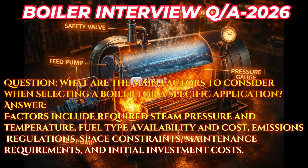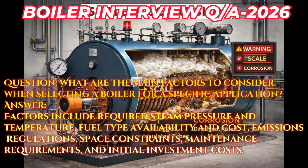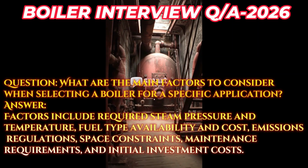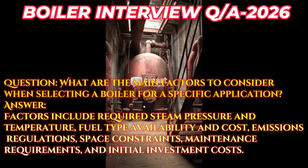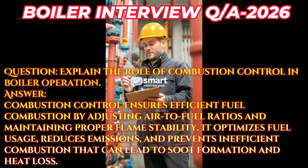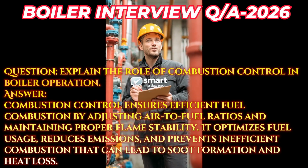Question: what are the main factors to consider when selecting a boiler for a specific application? Answer: factors include required steam pressure and temperature, fuel type availability and cost, emissions regulations, space constraints, maintenance requirements, and initial investment costs.